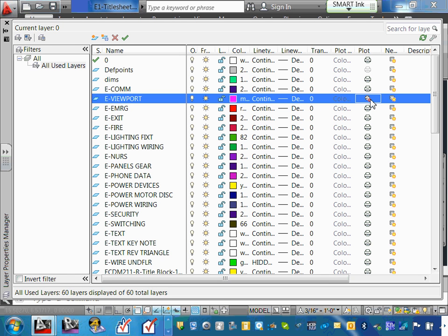And when I send it to the plotter, I want the plotter not to print the viewport because it looks like crap. Looks like another box. One more time. What I'm controlling here: I created a layer, I named it viewport, I gave it a color, and I set it on non-print, meaning don't print it. Can I have thumbs up, Chad? We understand that? Okay. All right, so that's good.